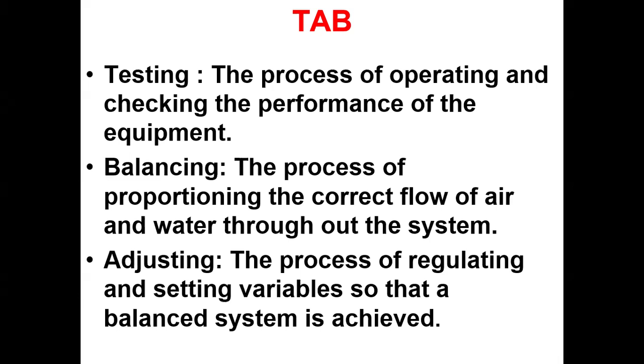And the other method is smoke testing. Smoke testing is much more reliable. Why? Because we can easily detect the leaks from the specific ductwork itself. So this is done before the installation of insulation. Otherwise, you can't detect that. Okay, so this is the concept.